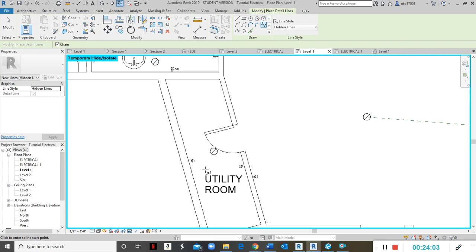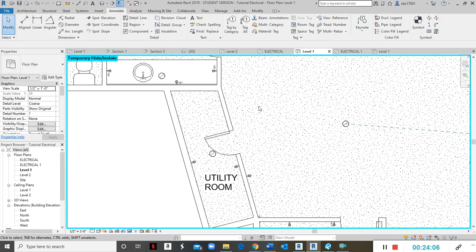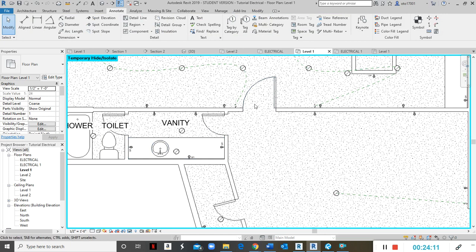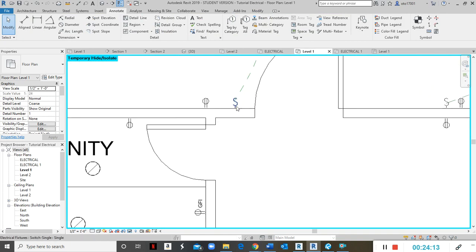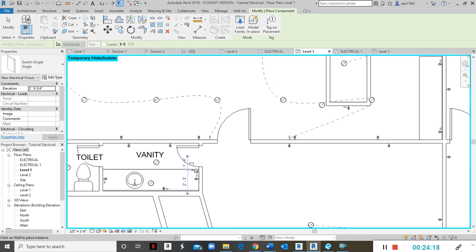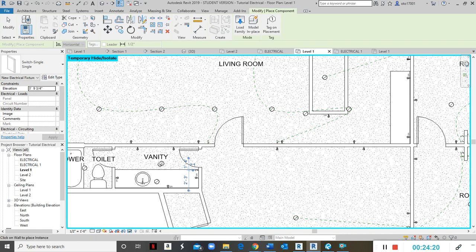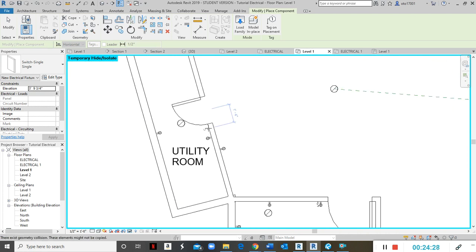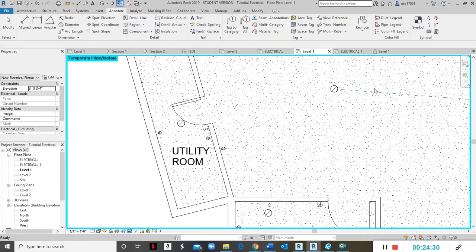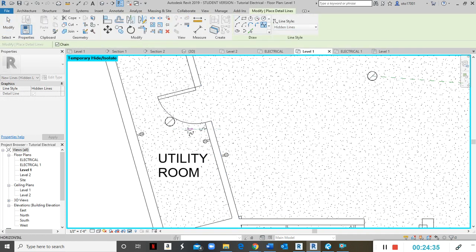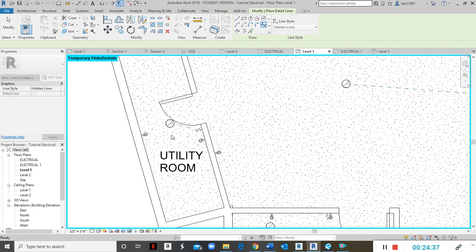And go. I was supposed to put a switch here. I did not put a switch there. Let me do that now. I did not even put one here either. Okay, so click on the switch. CS, have one in here. Control that light, and then this light, and then have one in here. There we go. So now detail line, hidden line, spline, and then here to that is done.